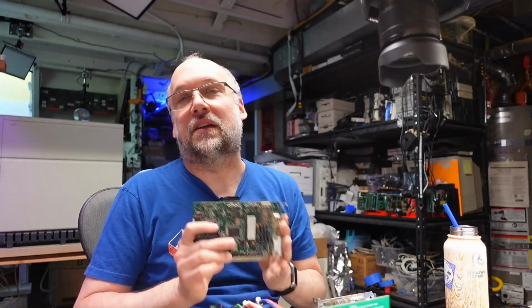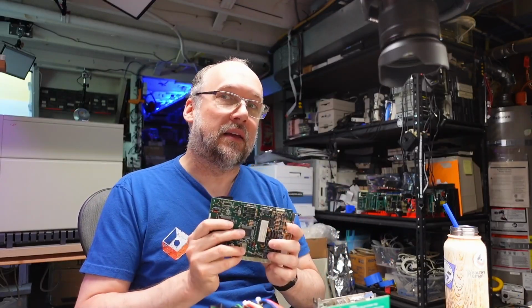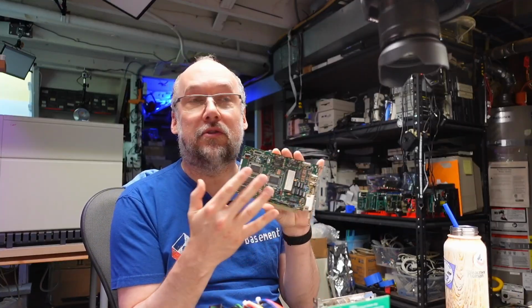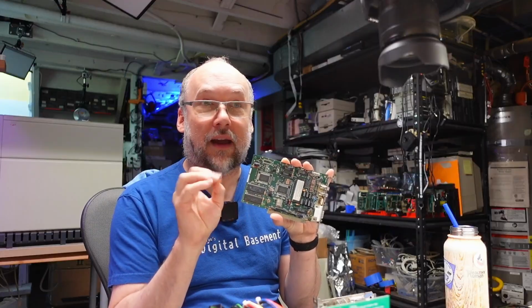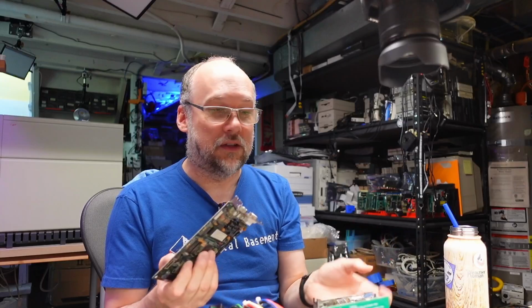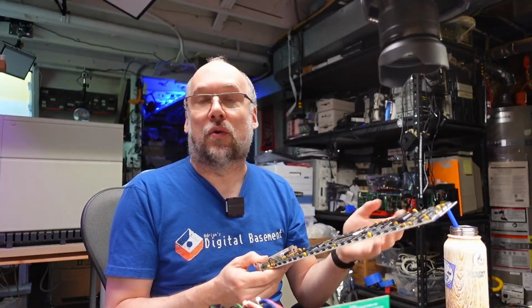Okay, so you've seen everything on the CGA card that happens with the stock card, with the flashing and the snow and stuff like that. Now back to this VTEC card. So they re-engineered the way the memory access works so you don't get any snow. But the thing is, if you have a card like this that has no snow issues, typically when you do a DIR command, you're still going to get that flashing. And that's because the IBM PC BIOS can't tell the difference between a real CGA card and this re-engineered CGA card. And that flashing routine is actually stored in the BIOS code itself, or maybe in the DOS interrupt calls itself. And therefore you get flashing.